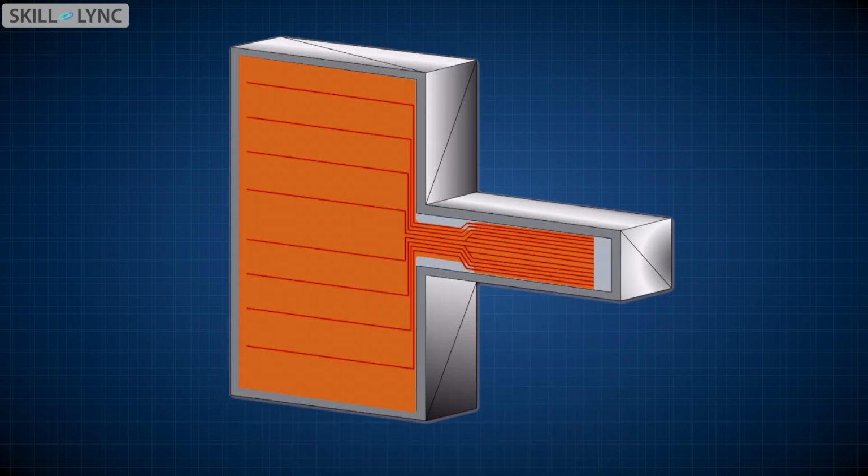Now, the fuel chamber has a large area compared to the throat of the nozzle. When fuel flows from the chamber to the throat, some of the fuel gets separated from the wall. So in this separation gap, there is a drop in static pressure. Now when this pressure drops lower than the vapor pressure of the fuel, the boiling point of the fuel naturally drops. So it will start boiling and vaporize.